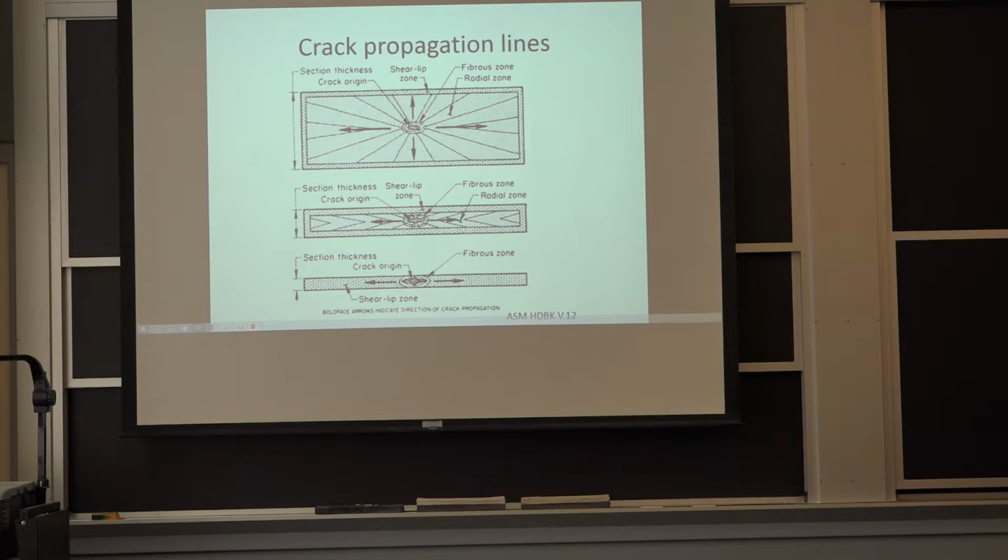Maybe there was a notch in the surface, but essentially something happened at those 3 locations to make the crack initiate. And it took time for those cracks to initiate, because if it had happened the very first day this axle was used, you'd have cracks all around it, and we don't. So this is an intermediate situation where there were deficiencies at the initiation sites.